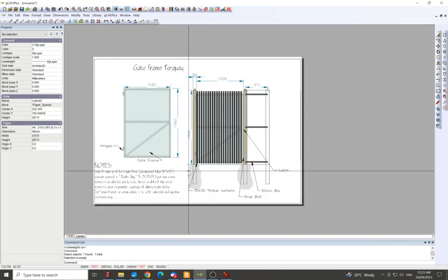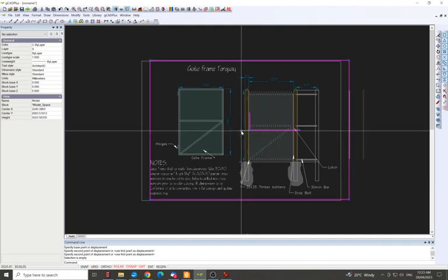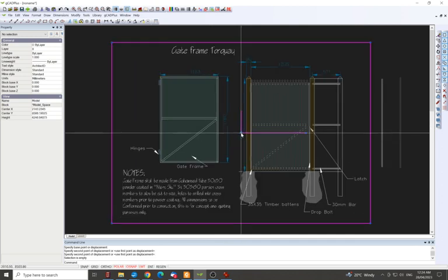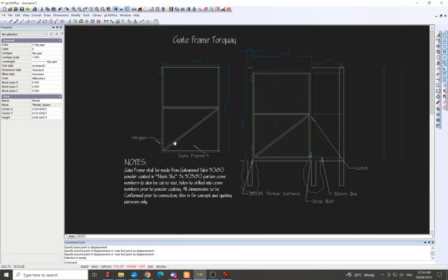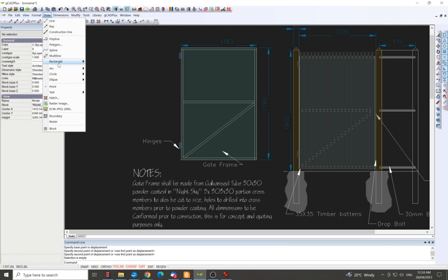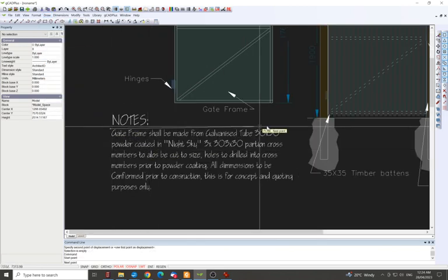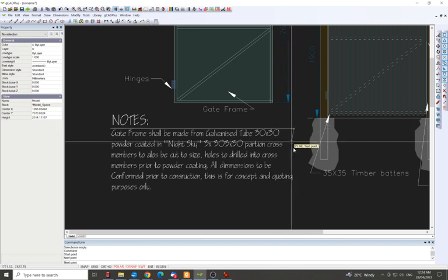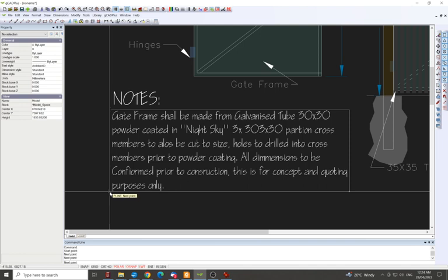All we've got to do, grab this picture again, and move it this way, and maybe down a smidge. If you want to be very fancy, but you don't have to do this. And I kind of like this little thing, so you can go draw, polyline, and now we didn't know the measurement for that, so let's hope we can line that up.